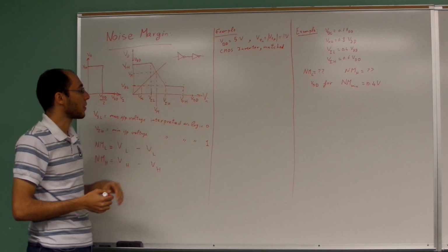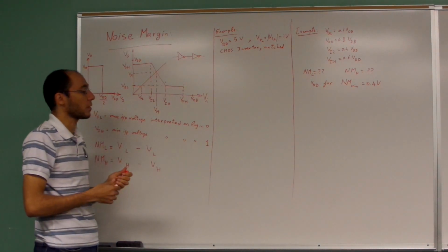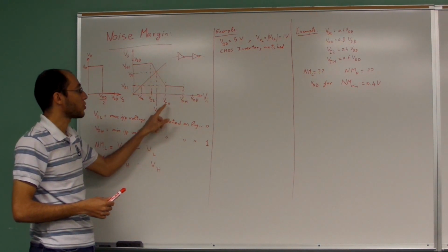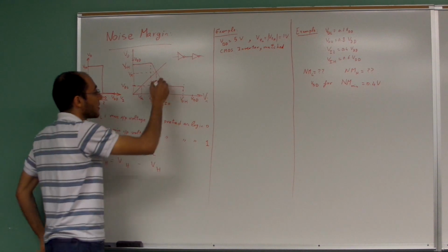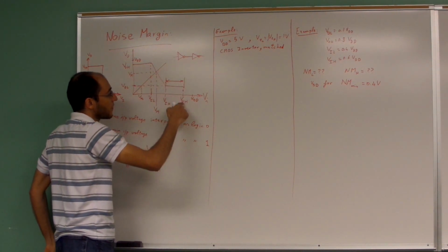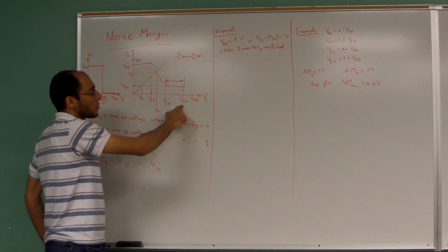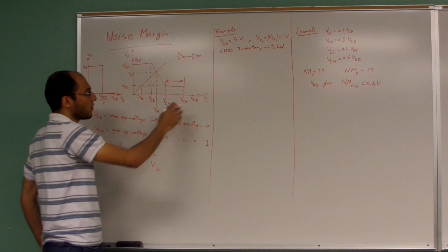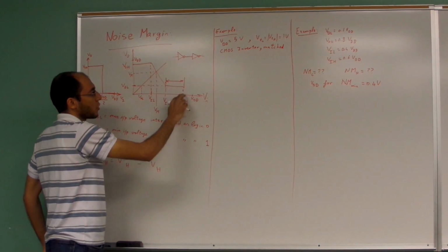If you want to give a logic 1, you should not give a value less than V input high. This defines the noise margin. Ideally, you're going to be giving VDD, which is supposed to be close to V output high. Let's assume, for instance, that VDD equals V output high, so these values coincide.